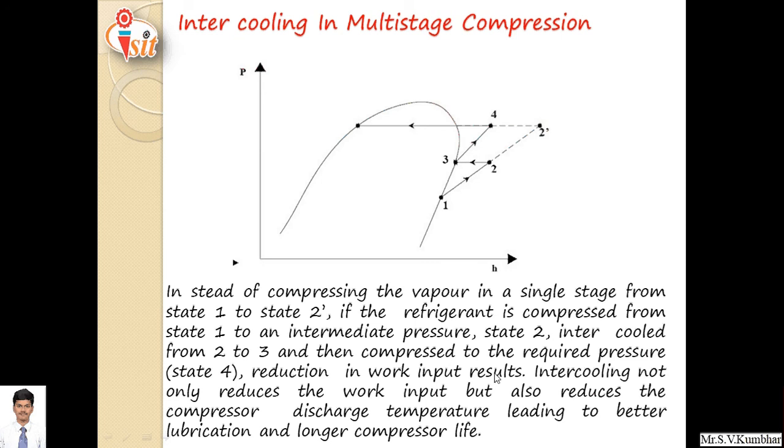So intercooling not only reduces the work input but also reduces the compressor discharge temperature, leading to better lubrication and longer compressor life. That's why in most dairy or chilling plants we go for multi-stage compression.